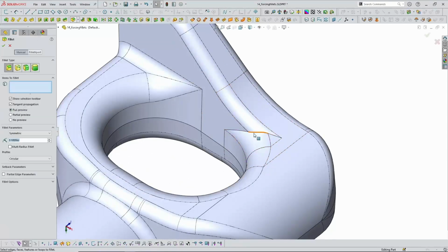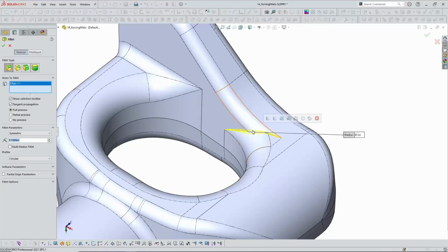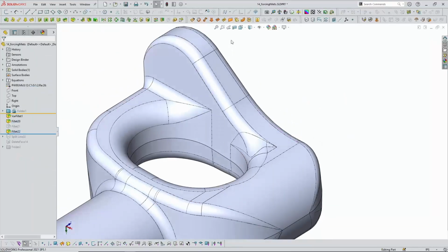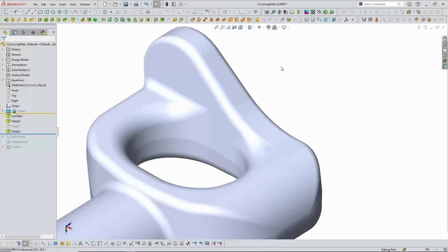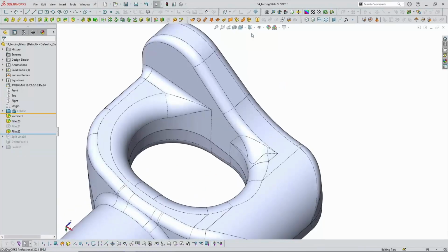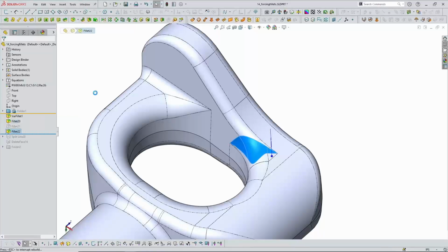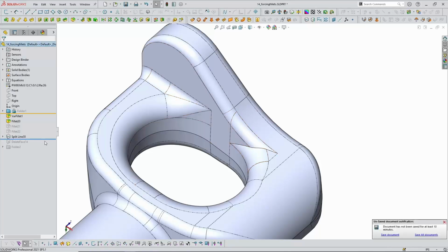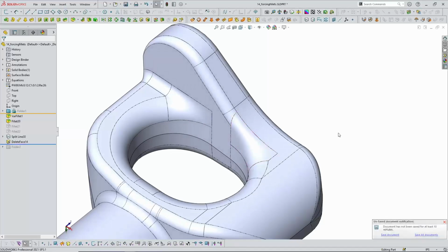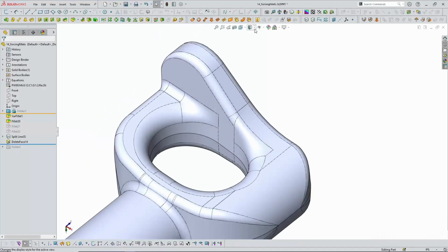I could look to just put a very big fillet. I'll just try and put the biggest possible fillet that blends. Oh, okay, yep, just keep going up until it works. But sometimes this doesn't work, sometimes it doesn't build. This is probably close enough, but the more manual workaround is to use split line, create this nice new kind of area for this blend to live in, and then force these two dissimilar fillets to flow into each other with the delete face tool.